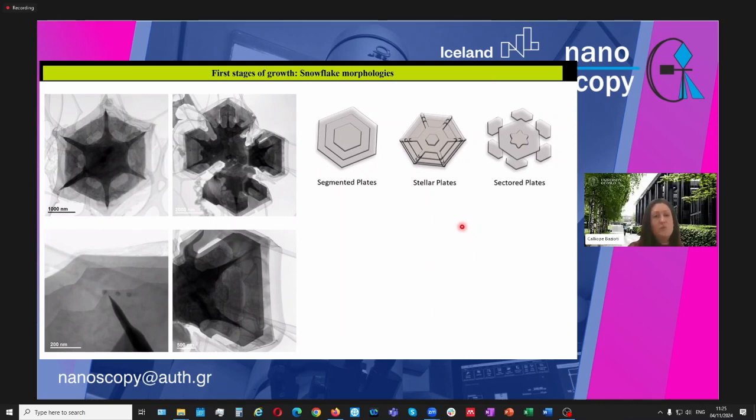And most importantly, we introduced a holding step, meaning that we did a pre-annealing step of our bilayers before we started the real growth process, in order to give enough time for molybdenum to diffuse and reach the surface of the melted copper.